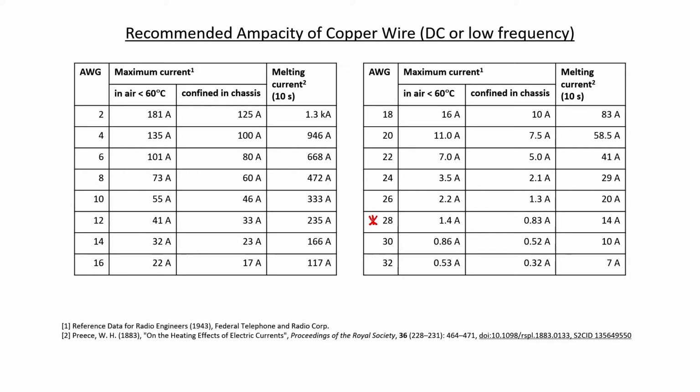It can melt insulation, or it could even start fires. If, for example, you have a wooden enclosure, it's worth keeping in mind that wood can ignite at temperatures as low as 260 degrees Celsius. So if you have copper wiring nearby a wooden enclosure, and the copper wiring gets hotter than, say, 260 degrees Celsius, then you could have a very dangerous situation on your hands. The copper could start a fire before it would melt.